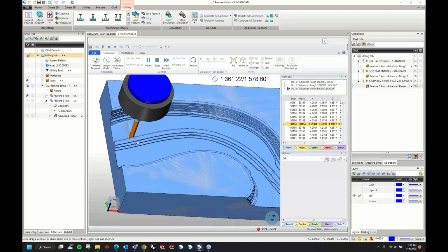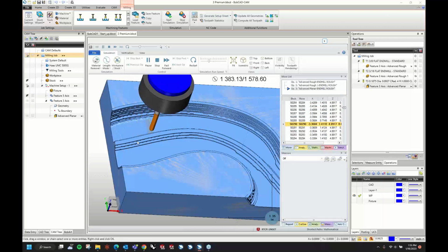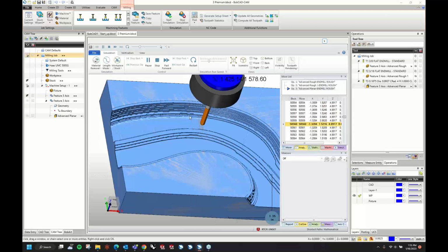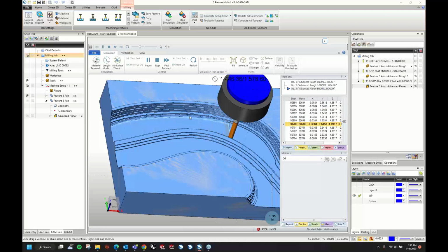And this is just going back and forth throughout this channel. So if you're trying to maintain as much with as few links as possible, this is probably going to be a little difficult to find the right angle. This angle works pretty well at doing this. Looking at the toolpath, it doesn't look like it's going to link a lot. But it's not going to be really smooth with the contour of this shape. So if I want to try to follow that a little bit, I'm going to have to play around with my lace angle.